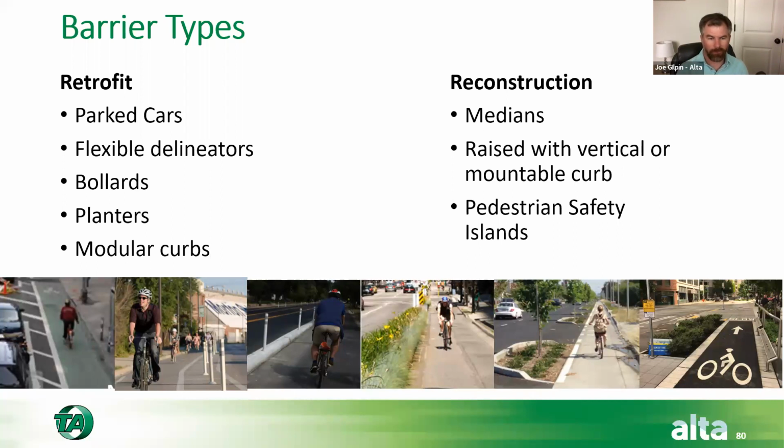It was a pole or a tree or something like that, and that stopped an errant vehicle from hitting them. And so, there's different ways to look at that. I looked into lower speed clear recovery zone research, and what I found was very inconclusive from a national standpoint. A lot of the guidance that's out there seems to have been just given a number without actually showing that it's effective at low speeds. And so thinking about the type of roadway that you're on and the speed that you're expecting can influence whether or not that's within the clear recovery zone.